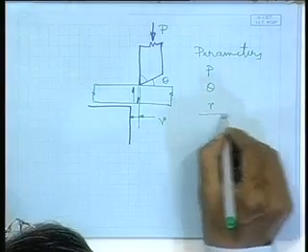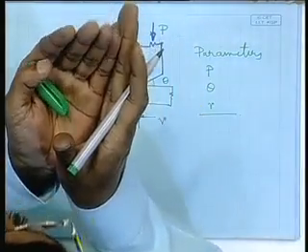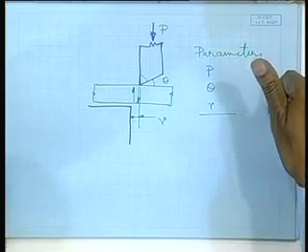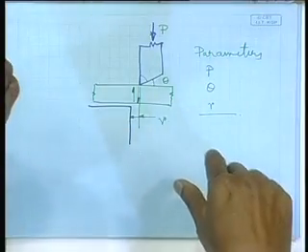What are the other advantages? That is the cutting edge. You get a very high quality cut edge, because when you are cutting by shearing you get a smooth cut surface. That is important, because that cut surface will be further aligned to some other plate for further fabrication, maybe you will have to weld. If the cut surface is smooth, then you get a better joint, a better weld. If the surface is very rough and uneven, then obviously your welding will also not be good. So, that is another advantage, a very good, smooth cut surface.